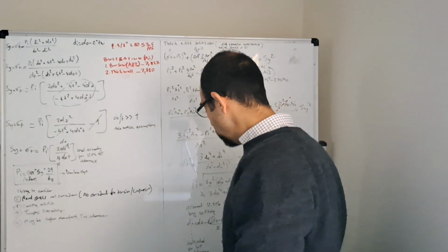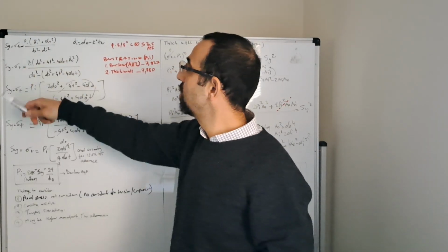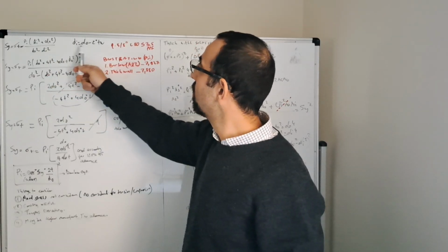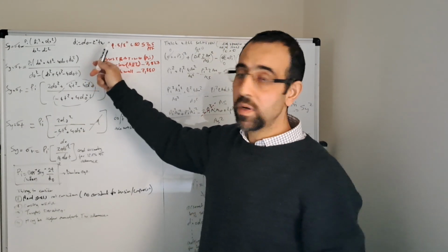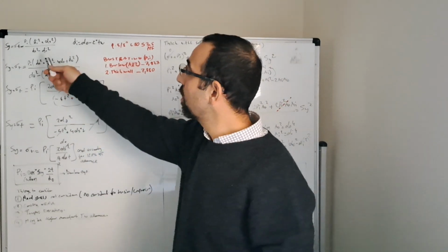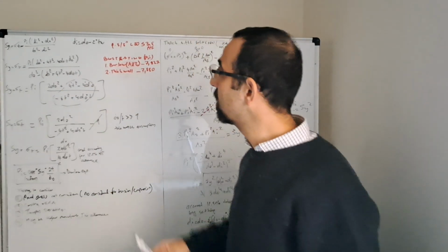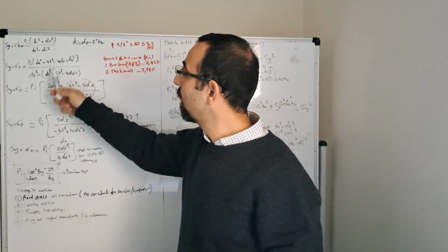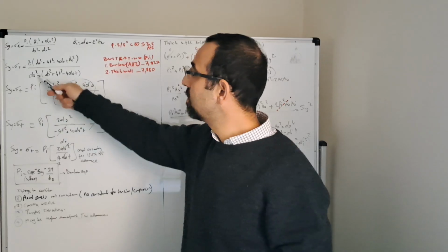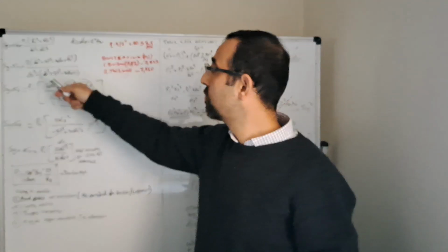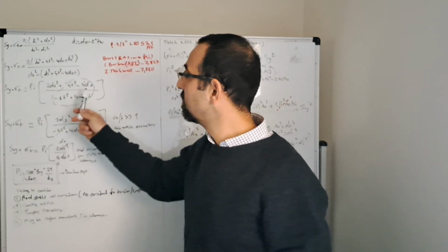Let's go to the second page. So we carried the equation from the first page, and then we put our wall thickness equation here, and the wall thickness here, as you remember, is the nominal wall thickness. So we are going to replace the inner diameter with the outer diameter minus 2 times the wall thickness, and if we replace that and do the transformation, we can see that the outer diameter square, which is the outer area, cancels out, and then you are left with this equation.